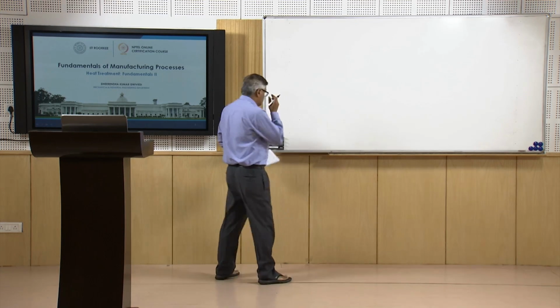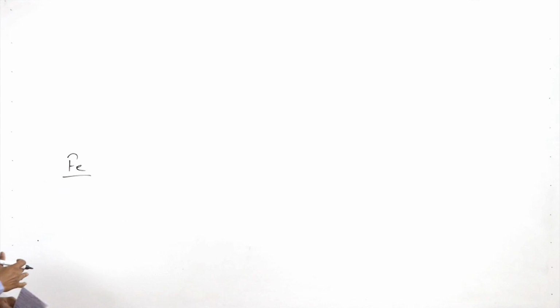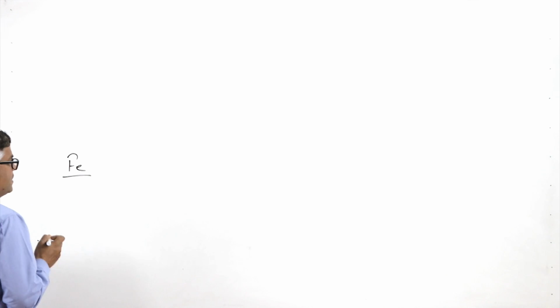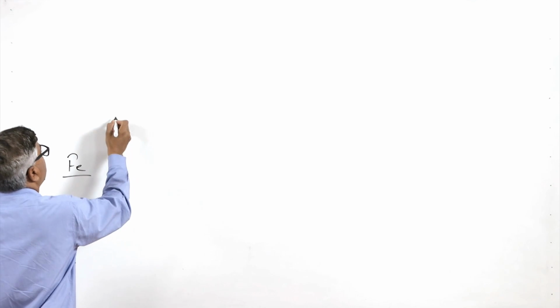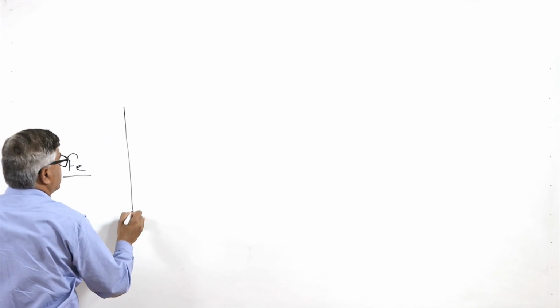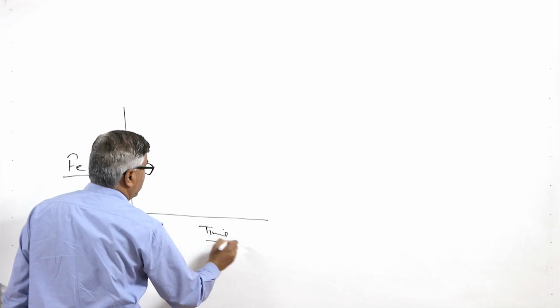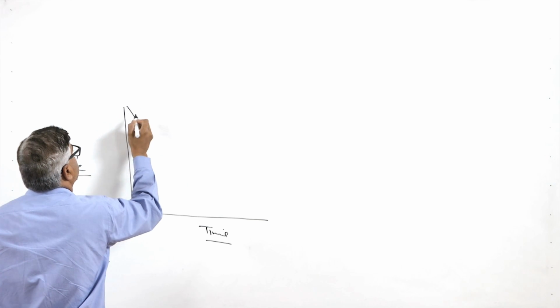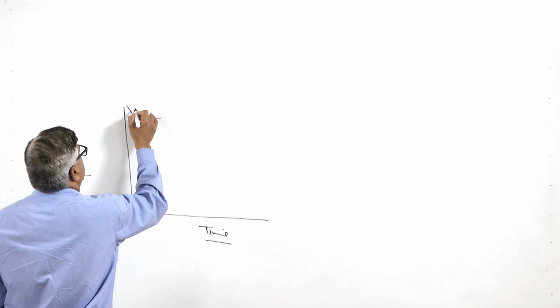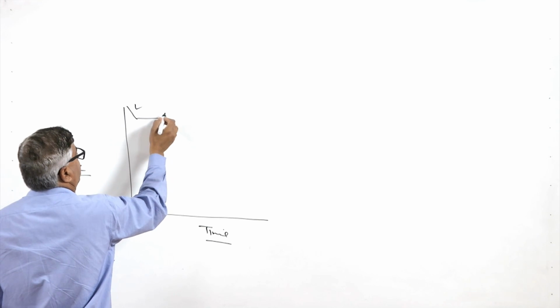So steel is an alloy of iron and carbon, which forms an interstitial solid solution. But iron in its pure form, when it is cooled from the molten state to room temperature gradually, as a function of time, the kind of curve that we get becomes like this. This is the constant temperature, above this it is liquid, and this is where it will be solidifying.